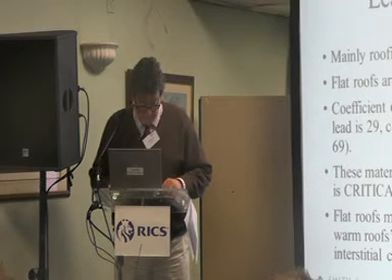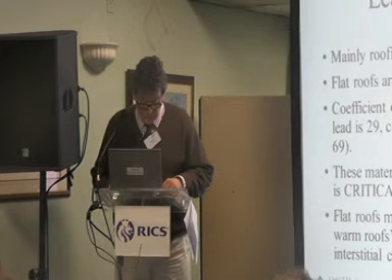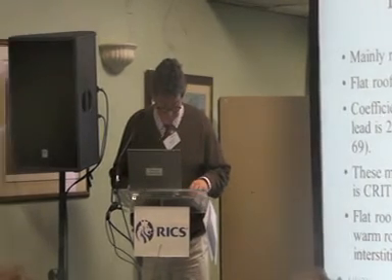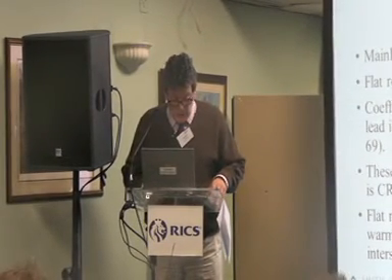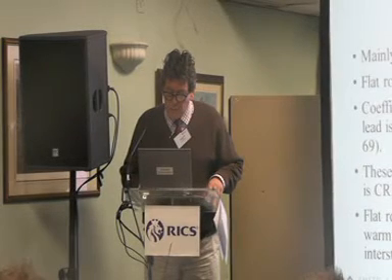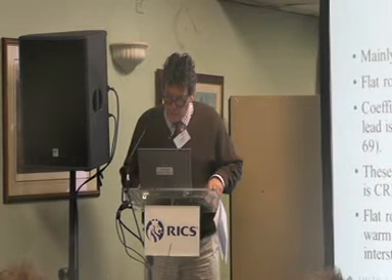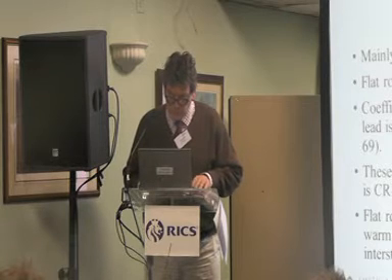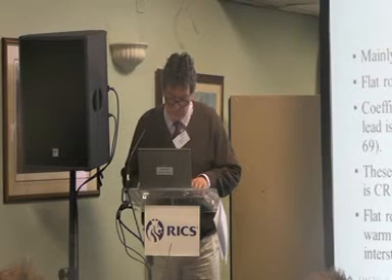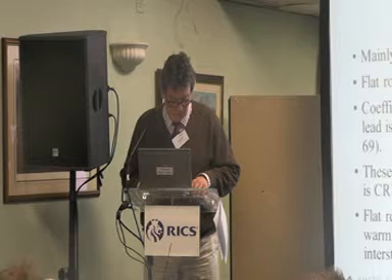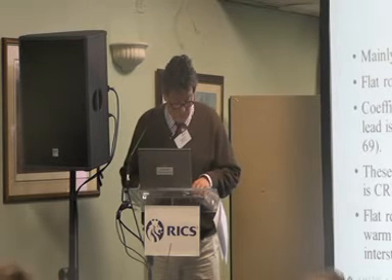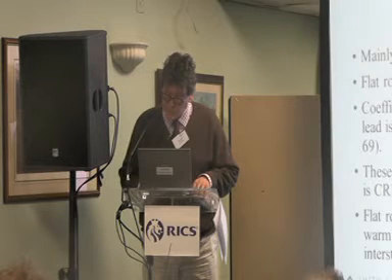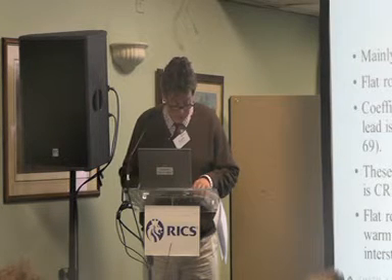Moving straight on, I want to talk a little bit about rolled sheet roofs, lead and copper work. I'm not going to worry about other forms of lead and copper. I'm just going to talk about rolled sheet, because unless there's a special requirement to talk about slab or anything else, these are the most usual materials you're going to come across. And the first thing to remember, of course, is that flat roofs are not flat. You need a minimum of 3 degrees of slope to allow the water to run off.